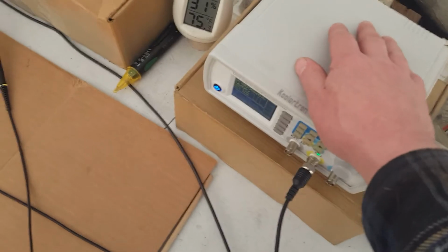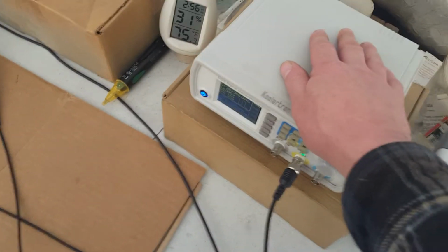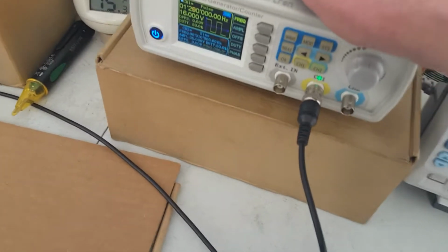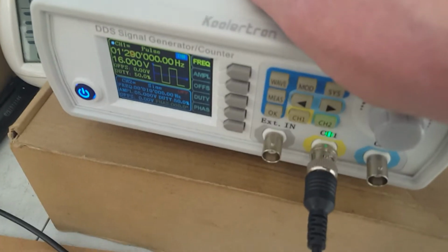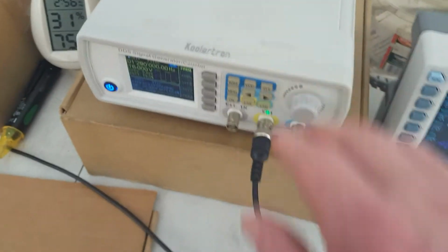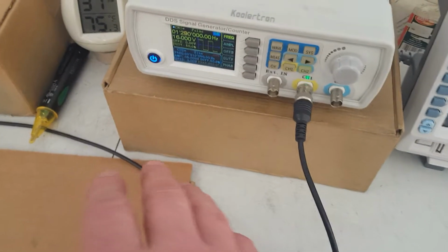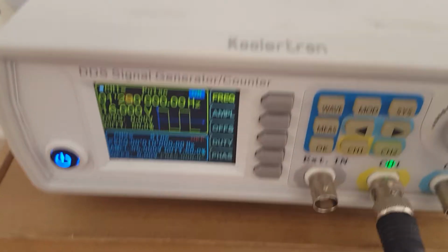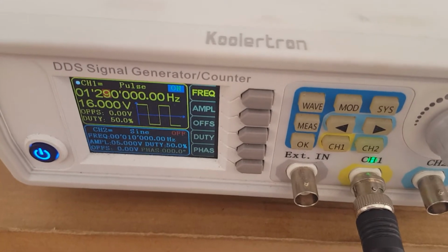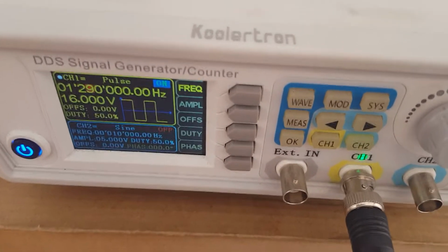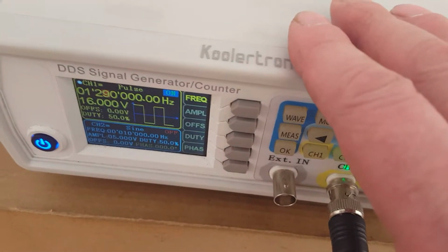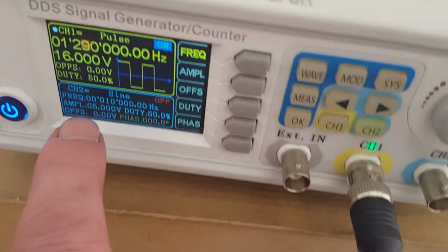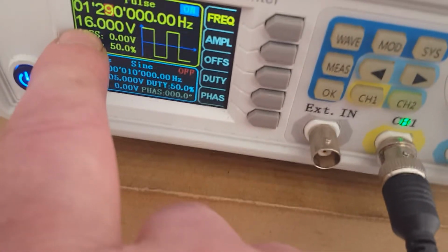Yeah, let me explain this, guys. I'll try to be quick about this. This is my frequency generator, also referred to as a wave generator or a function generator. I get to control the output voltage. The current is limited by the manufacturer to 100 milliamps. It's 1/10 of an amp. That's the most it could put out, and I can control the voltage from 0 to 20.